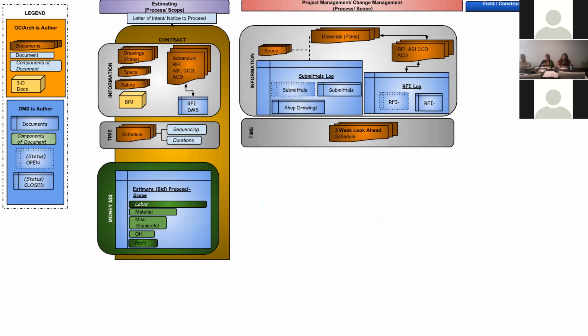So when you get on multiple floor projects, they can be extremely dangerous because there's so many people working on so many different levels. And if somebody drops something, well, it'll transfer down. So they will look at 3-week look ahead schedules in regards to procuring material, what's going to be happening, sequencing the building. And we want to be looking at the sequencing component of that.